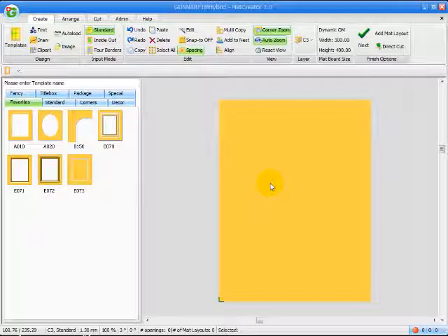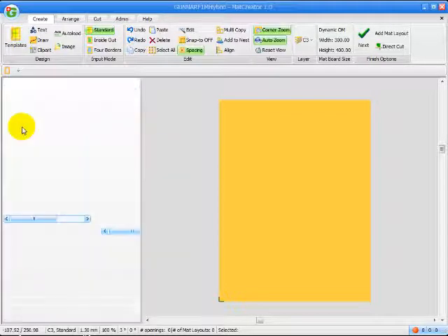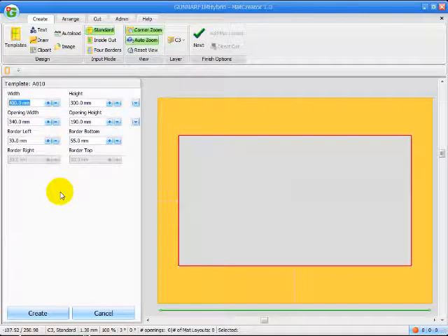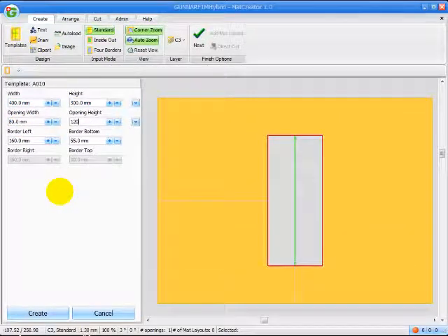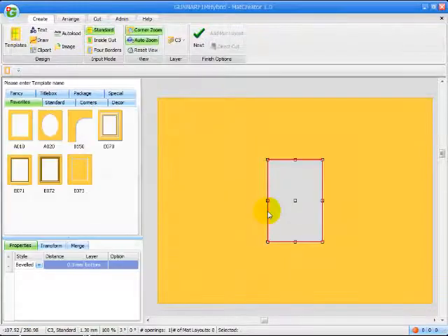In this GMC tutorial video, I'm going to demonstrate the features of our transform tools, which will allow us to change the scaling, rotate objects, mirror image objects, and size objects. So here, if I create a new object or shape, I'll just use the rectangle as an example. I'll just make it small to start with, make it say 80, tab 120, and then click create.